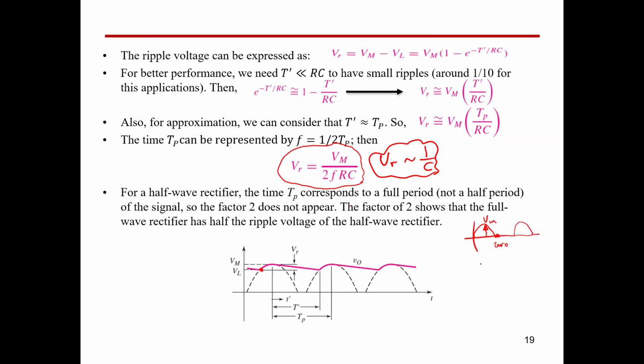So the ripples equal the maximum, but this is in absolute value, measured in volts. If you would like to calculate ripples in percent, we can divide these two, or normalize the value in order to get it in percent. The normalization is to the maximum voltage of the supply.